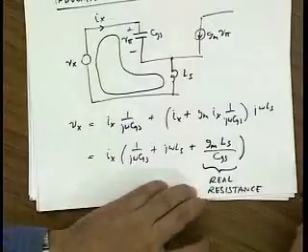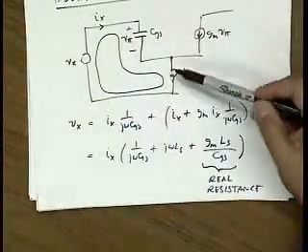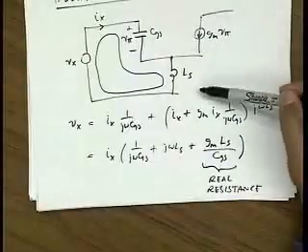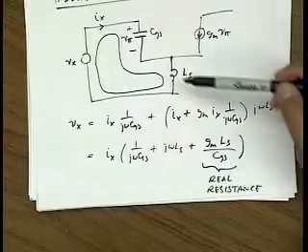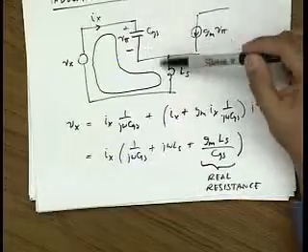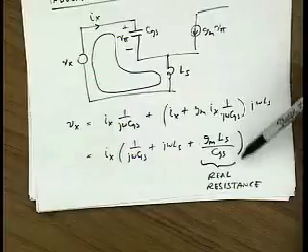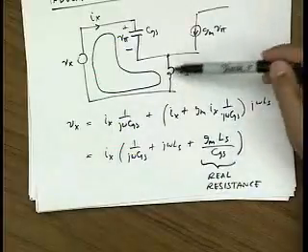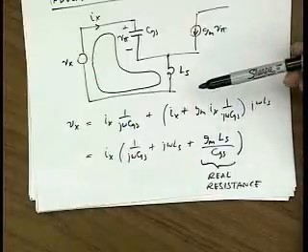Now this is neat because there are no resistors in the circuit, right? Everything's basically L's and C's and this transconductor, and this feedback actually synthesizes a real resistance for me. Okay? Now that's really nice. That was the big problem with the MOS device, in that its input impedance had a very small real component. Now we can see that we can synthesize a large real component by just using the inductive degeneration that's there anyway, right? That's part of the package parasitics anyway.